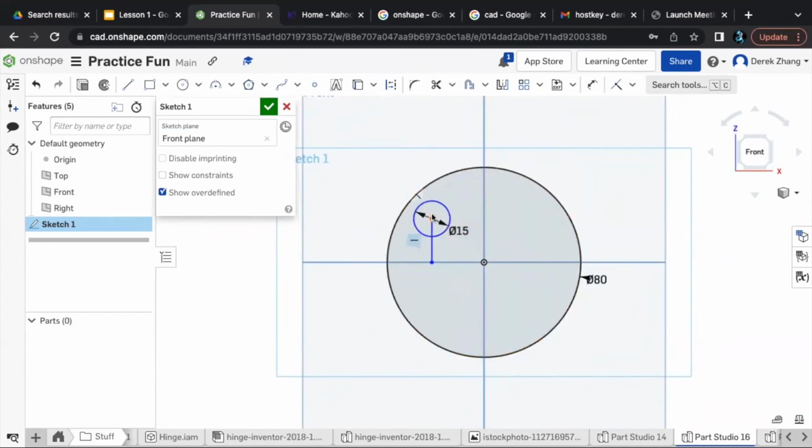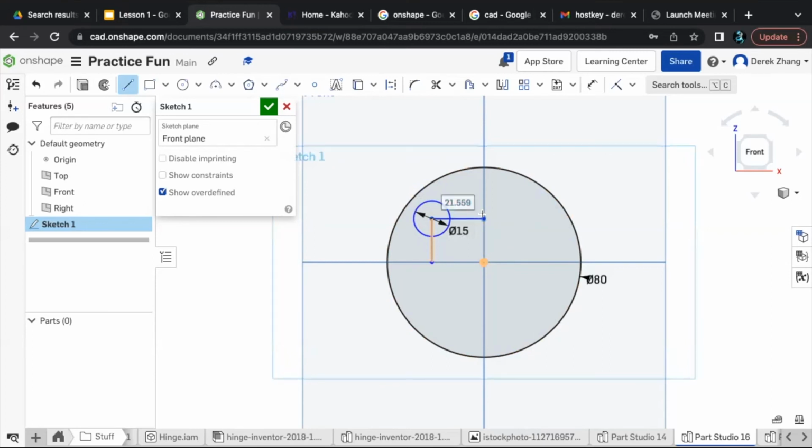So now we're going to dimension the first eye. Don't click on the circle, just hover over it so it turns yellow. Then click the line tool again. Click that once and then drag it over until you see the right angle again with the 2 stripes, and the origin is also highlighted. When you have it like that, you can left click and it should draw another line.